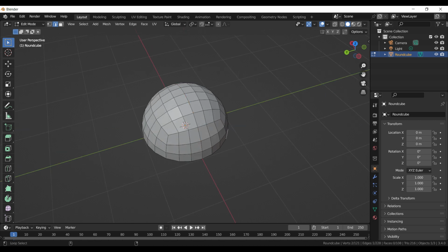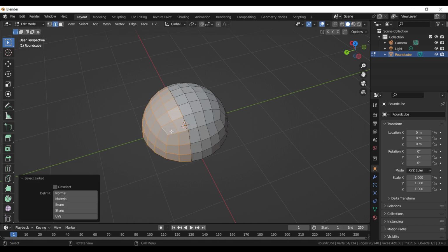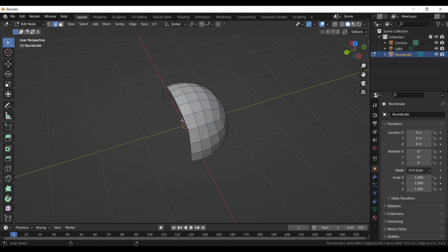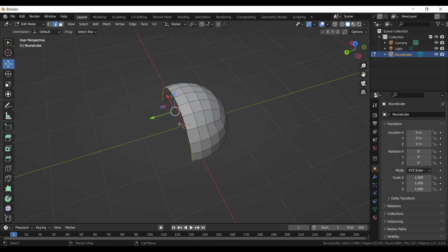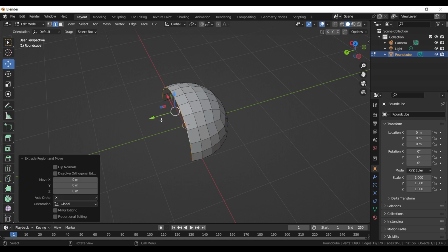Let's press Shift-Alt to select Edge Loop. Press V to rip region. Press L to select Mesh. Press X and select Delete Faces. Let's press Shift-Alt to select Edge Loop. Press SY0 to align faces along the Y-axis. Press EY to extrude along the Y-axis.